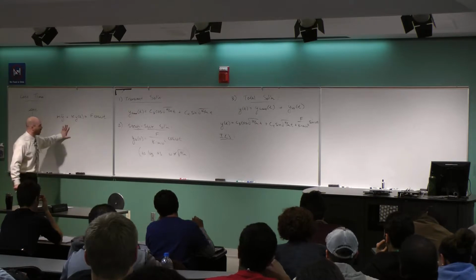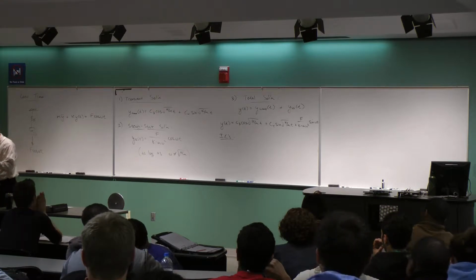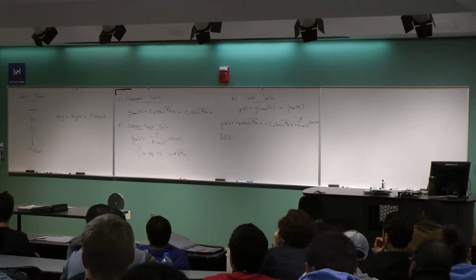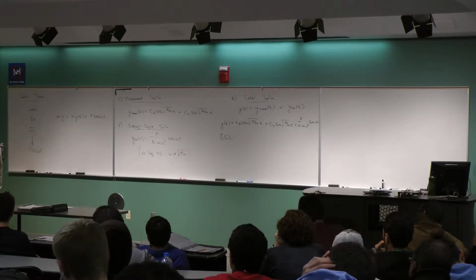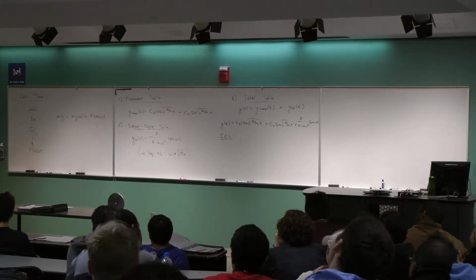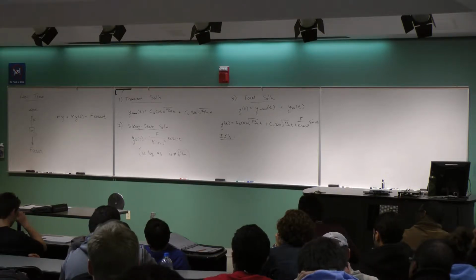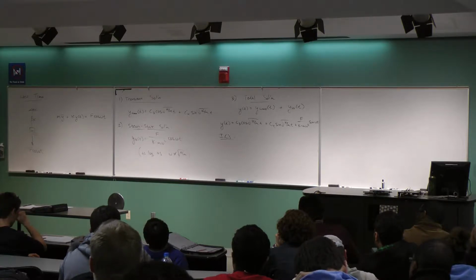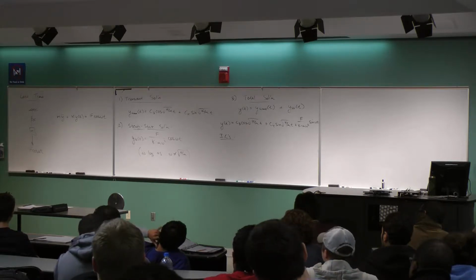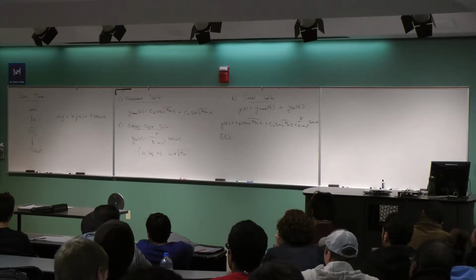Here's our governing equation. Here in lecture, I like us to think about, at the appropriate time, what the appropriate initial conditions are. So the free vibration problem, here's the statics problem, and we said the dynamics problem is now displace it and let it go. Those initial conditions were a non-zero initial displacement, and then 0 for an initial velocity. If I apply a forcing function, F cosine omega t, do I need to have any initial displacement in order for this thing to vibrate?